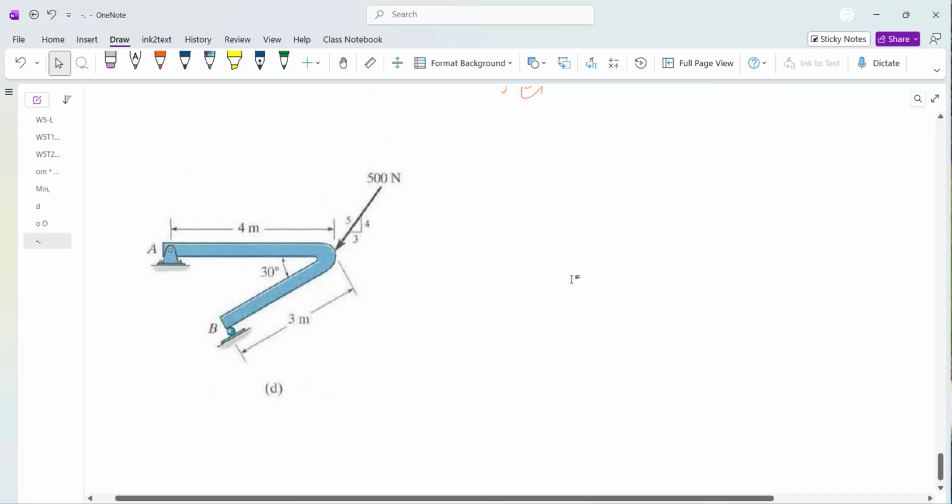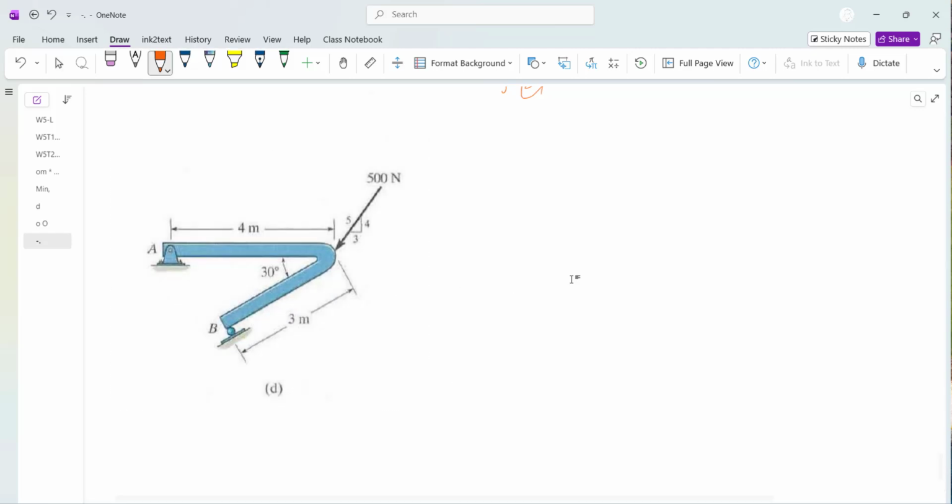Alright, so this free body diagram is only one rigid body, the rigid body of AB. So how can I free this from the universe? I intend to assume an enclosure. So this is my enclosure. The rigid body inside the enclosure is my free body diagram. Anything outside, including the constraint points or ground, these are attached to the universe.